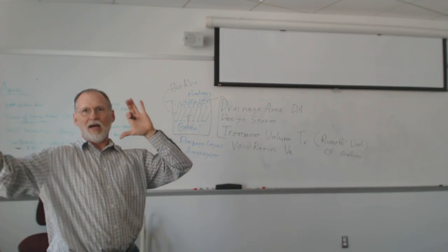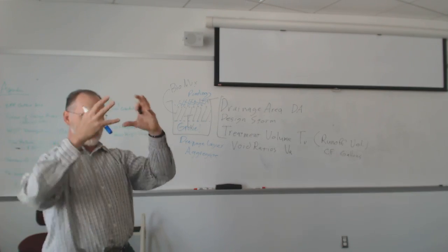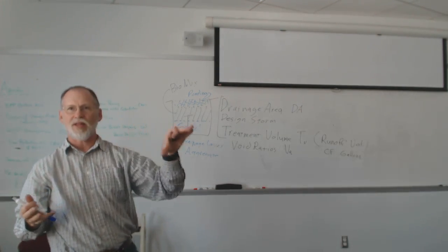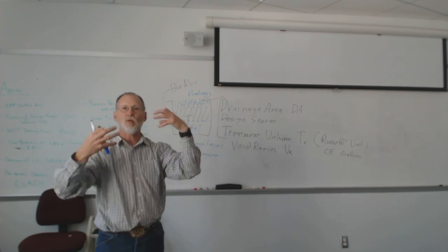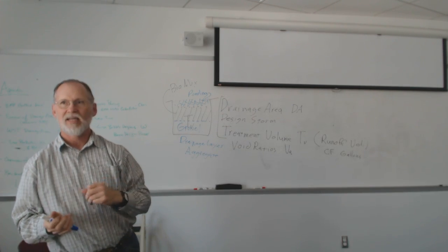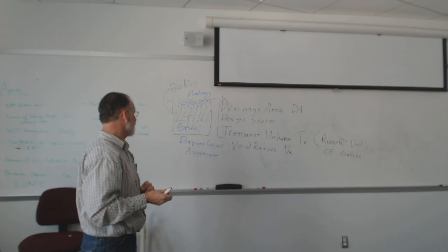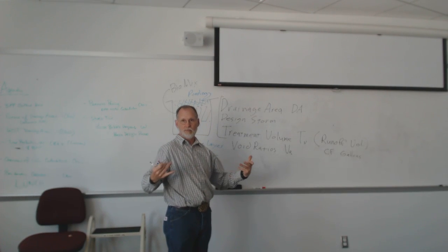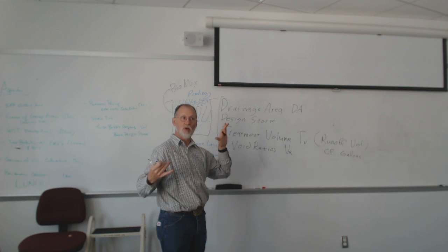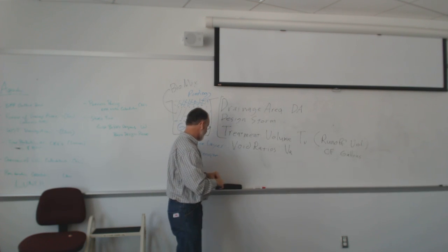If you picture a big clear box full of those stones, you can see where the air spaces are. If you filled that up with water, you'd be able to see the water in and around the rocks, right? The same thing happens at essentially the same proportions, no matter what your stone size is, as long as it's an open graded stone.